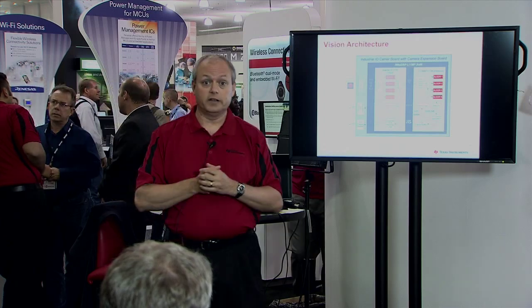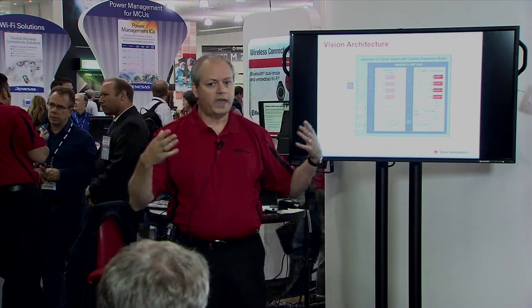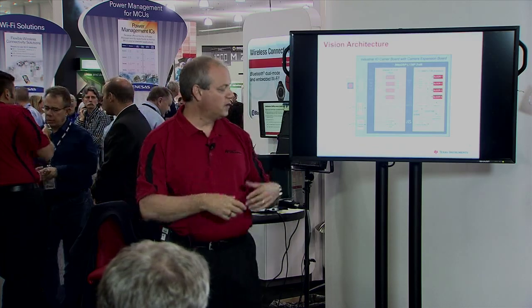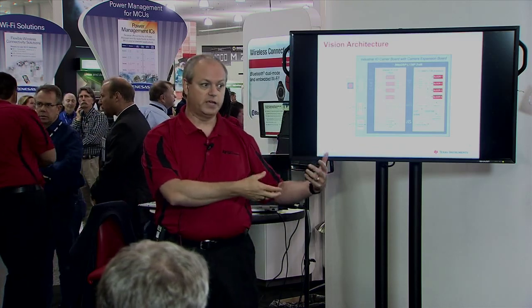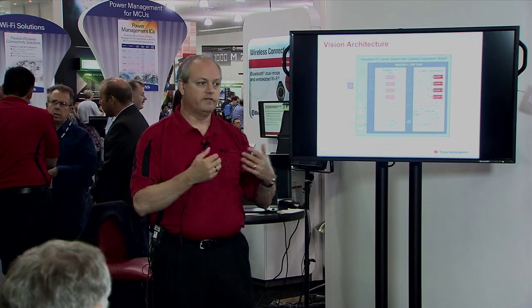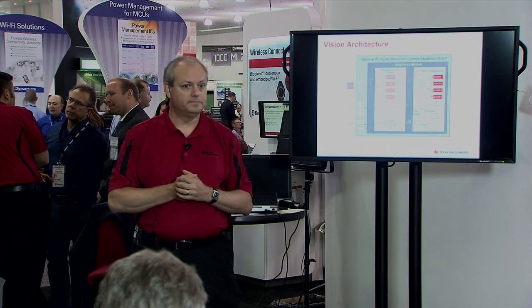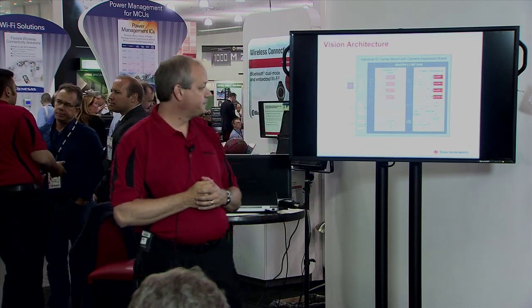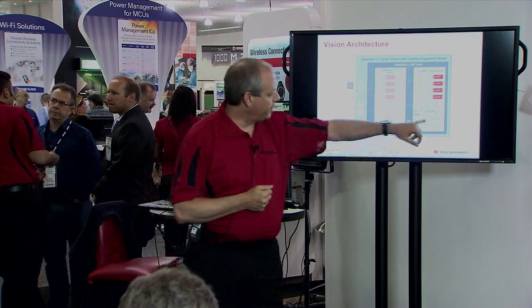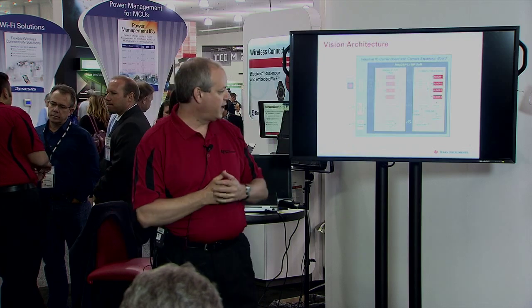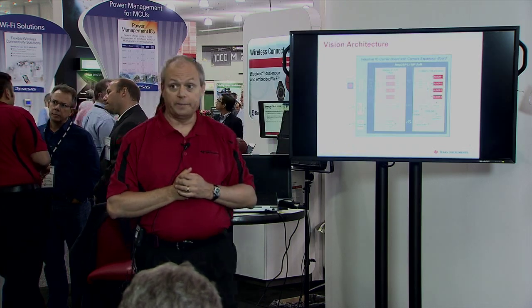In our case over here at the demo, we have a frame buffer present in shared memory. So the ARM places the frame buffer into shared memory, and then the frame buffer is scanned out by the LCD device to push that out to the actual display. And that you see right here, that it goes into the Linux frame buffer, and then Linux just pushes that out frame by frame.